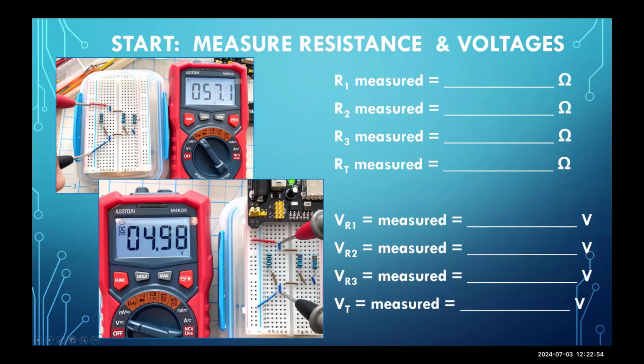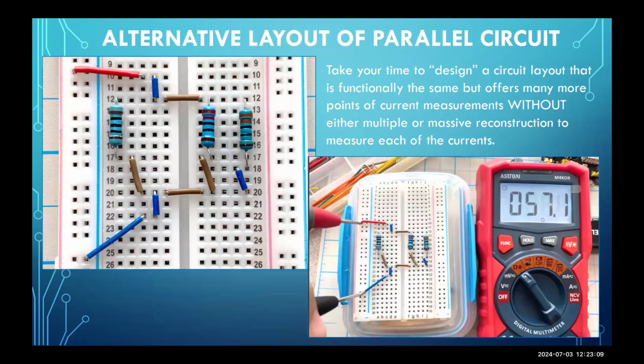Did you measure them individually before putting them on the board? Hopefully so. If you did, and you're confident these are the right resistor values, then you want to check your board connections. Are your board connections solid where they ought to be? In other words, if you look at this closely here from the previous slide, are they all matching electrically to make the proper connections like so? If they're not, one pin might be off in the wrong position, and that means one resistor is not connected properly. You will not be able to measure the total resistance as you desire. So that would be your solution for troubleshooting. Make sure you have the right resistor values and make sure the circuit is built properly.